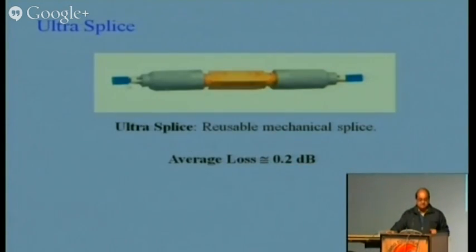So this is one sort of these splices. You can see here, you can insert your fiber from this side, and the other prepared fiber from this side, and in between there is a glass window. Through this glass window you can see whether the fibers have come near to each other or not. The diameter of this tube is very near to the diameter of the fiber.